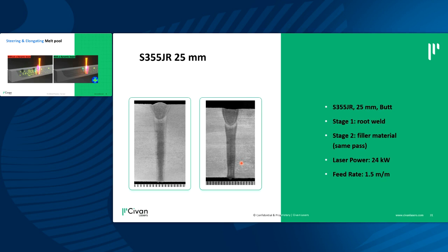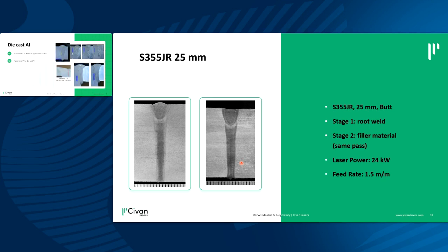And when using this method, we were able to weld die-cast material. What you see here in both of these examples are different high-pressure vacuum die-cast aluminum with less than 3% porosity. In both of these applications, it was a leak-tight part that needed to be welded. We also did some testing for welding of die-cast with other materials, either die-cast with aluminum series 3 or even die-cast with extruded aluminum.